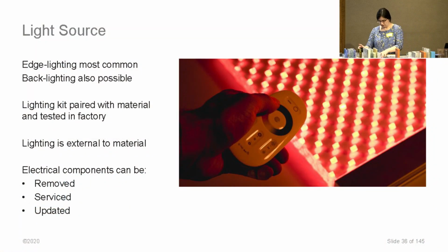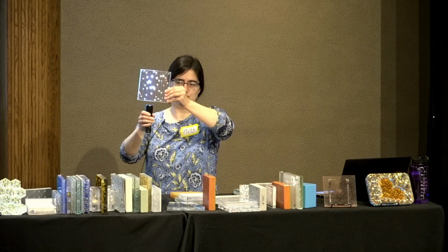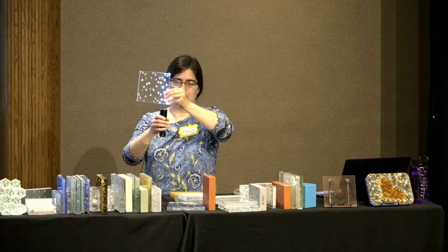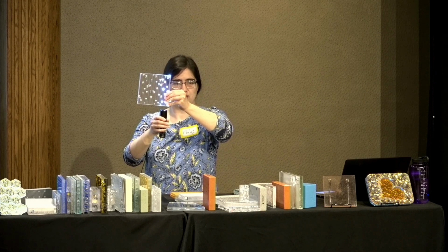I've been showing you this edge lighting effect. Like I said, this is sort of the standard. The advantage to the edge lighting system is twofold. First of all, you're using less lights overall. You don't have to light the whole square footage. It's just one or two edges. And then secondly, the light is never blocked off or held down by the material. So the strip light goes just in a little channel, and the panel goes on top.